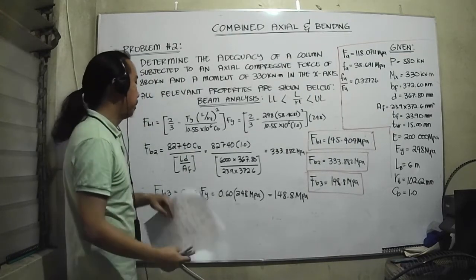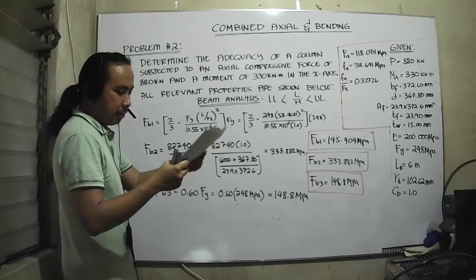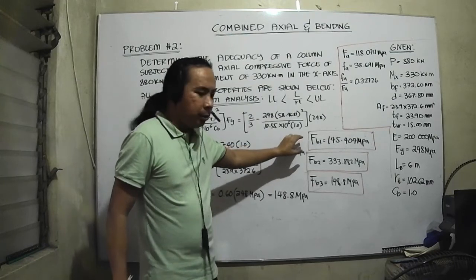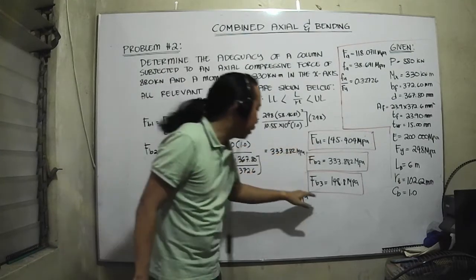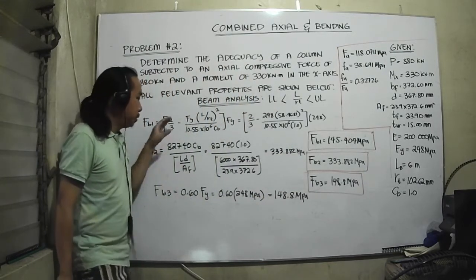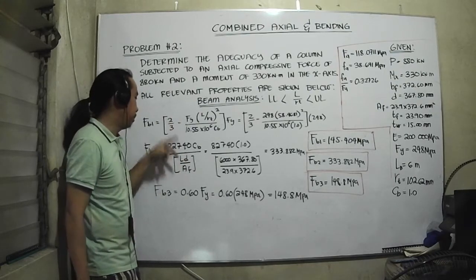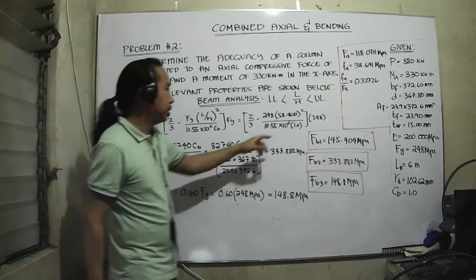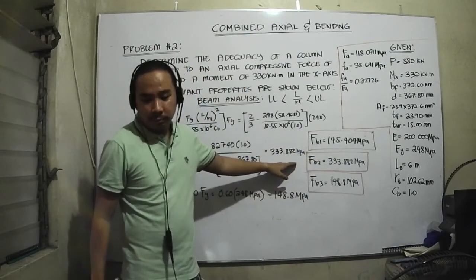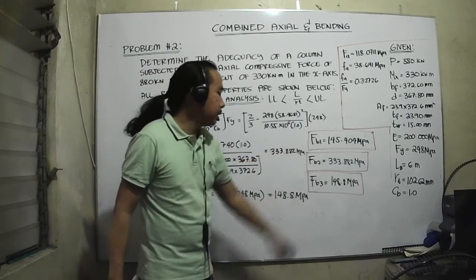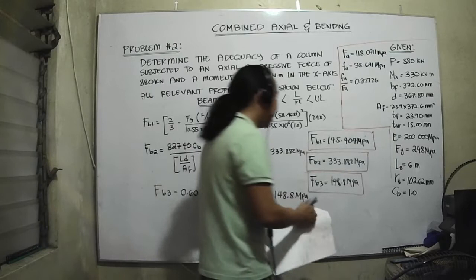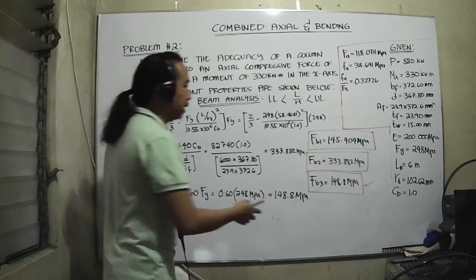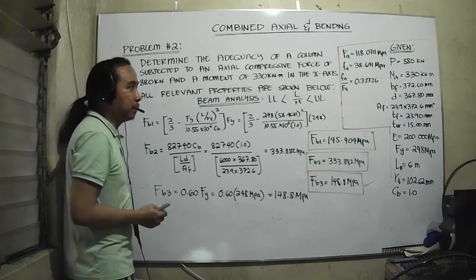So we solved for three bending stress values. Now the idea, I don't know if you remember exactly, is that you choose the higher value of these, but it must not go beyond 0.6 Fy. Between FB1 and FB2 we would choose FB2, but it should not go beyond FB3. So the winner of our contest here is FB3. We choose FB3. If you want to know how I rate the criteria of the contestants, just view the previous videos about beams.